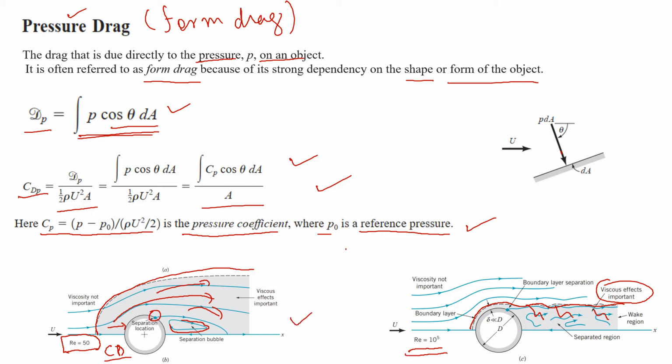So this is the exact concept behind this phenomenon that we discussed: what will be the drag force for high inertial forces? Inertial forces means that we have high Reynolds number, so the viscous forces will not be dominant, and in that case the drag force will not be dependent upon the Reynolds number. But for low Reynolds number flows, the drag force will be inversely dependent on the Reynolds number, and if we reduce the Reynolds number, then the drag forces will become more and more dominant. So this is the effect of the drag force.